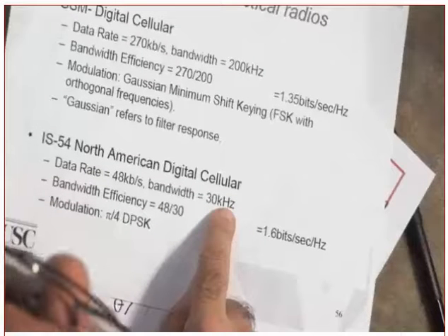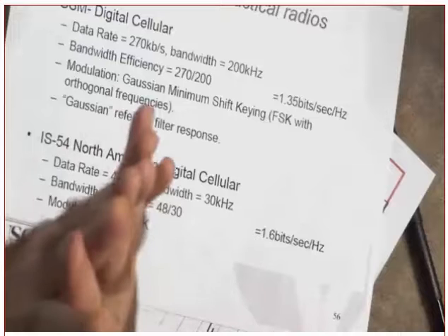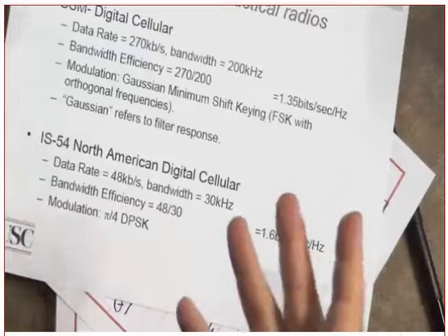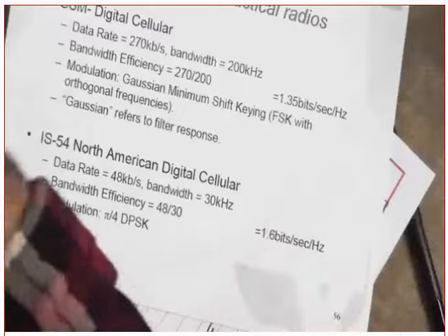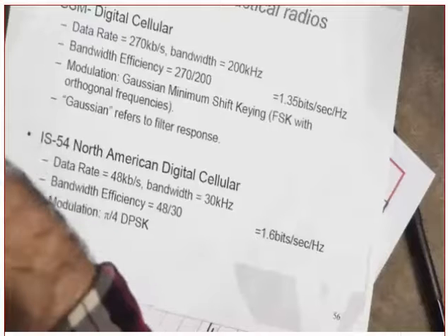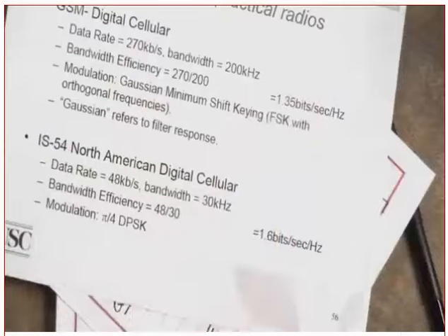That was the same band that was allocated to the analog phone. Did you understand what I just said? Now, when they brought digital technology, they did not expect all the customers to throw away their analog phones right away. So at the beginning, they used the same band. Some frequencies are time division multiplexed, and some frequencies are used as analog, using FDMA, frequency division multiple access. Did you understand what I just said or not?